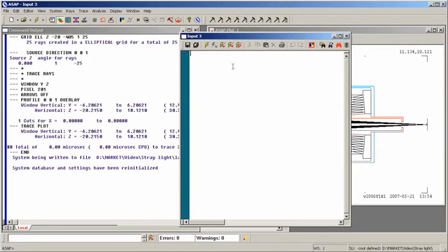So we'll begin here. The very first command I'm going to enter is system from cas. Recall that cas was the name of my binary file. It's the file that contains my system geometry and the optical properties. By saying system from cas, I'm reading that geometry into ASAP's memory so that I can work with it. I now want to add scatter properties to the object of interest.